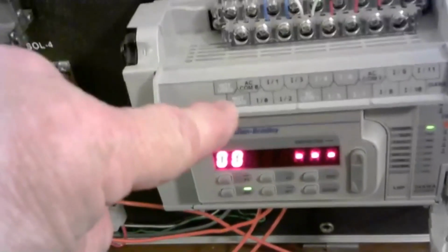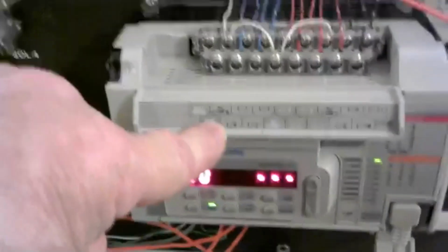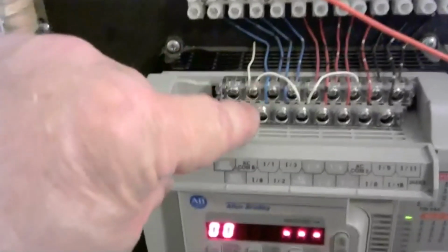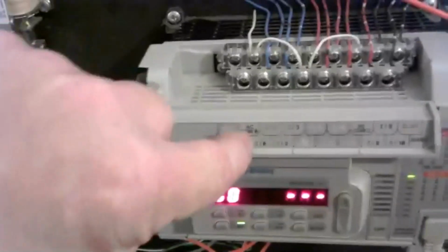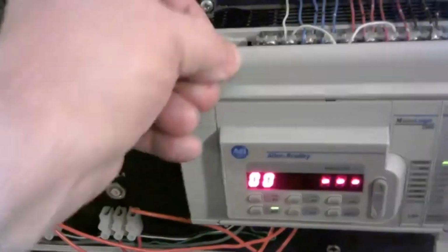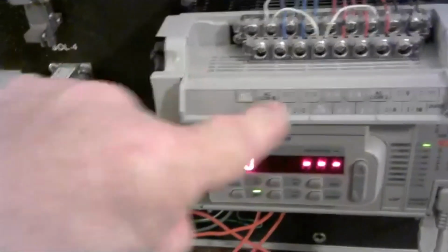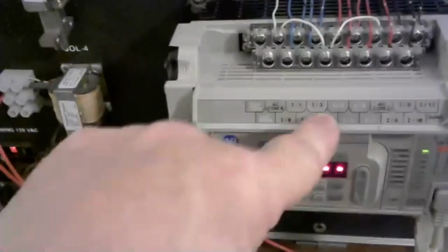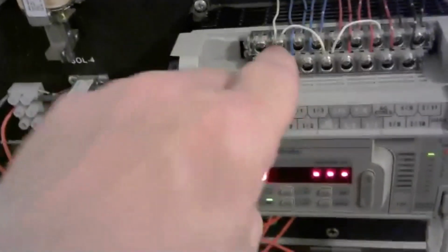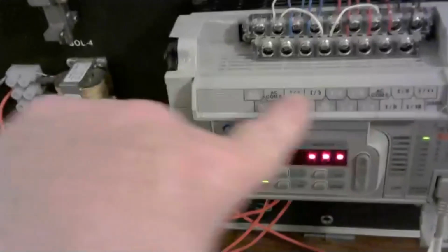And down here, it says I/0 is input 0. You can actually see where that wire's coming from, going up to that second terminal on the bottom row. That's the input 0. So this is actually on the fold down door, that you can tell by the labelings how to wire, or if you're measuring voltage coming in for troubleshooting purposes, you can read right there on that label what's what.